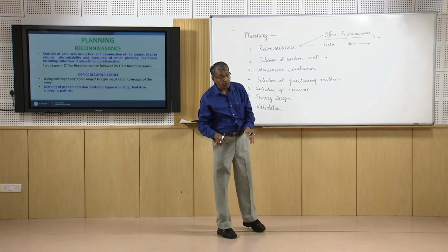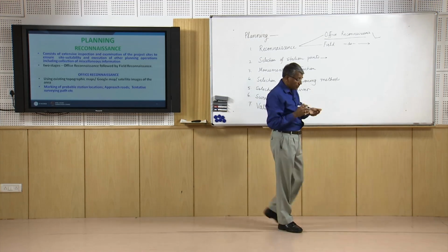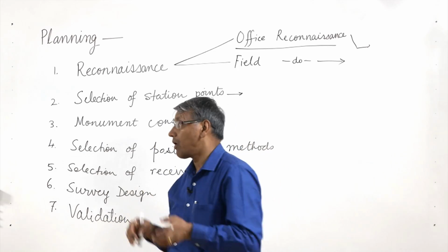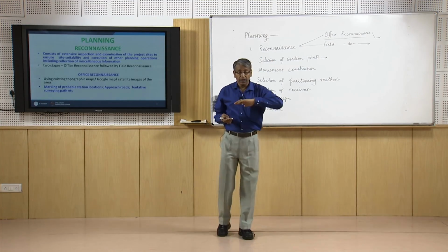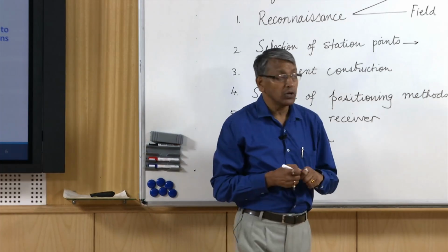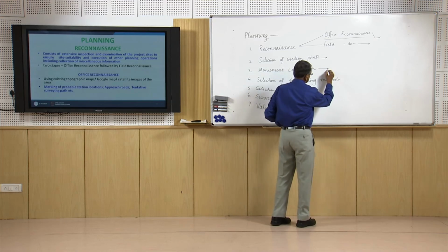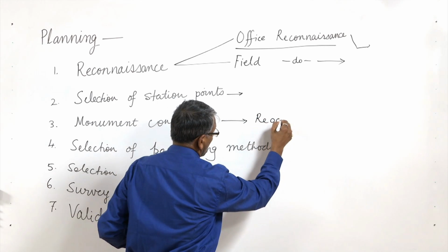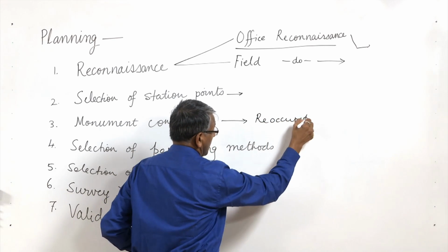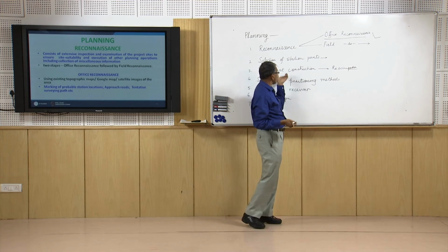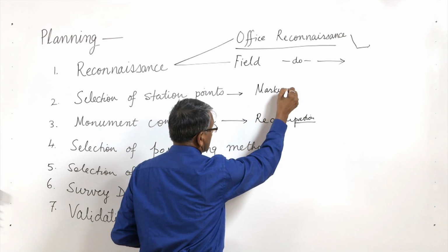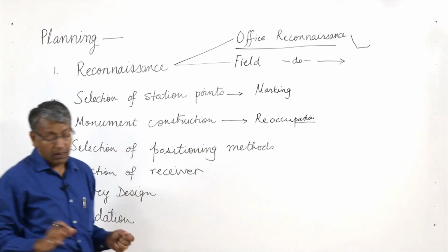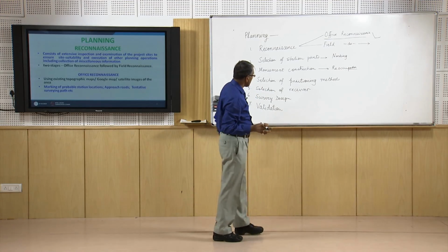marked on the ground, and if we need to carry out surveying for a long time, or we need reoccupation of the stations, then we need to go for construction of monuments. So if reoccupation is required, monuments will be constructed; otherwise marking of stations in the field will be sufficient.